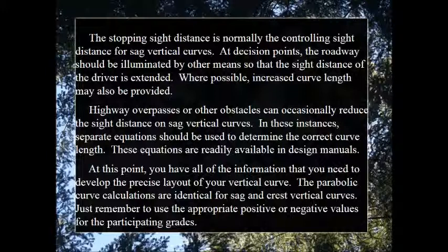At this point, you have all of the information that you need to develop the precise layout of your vertical curve. The parabolic curve calculations are identical for sag and crest vertical curves. Just remember to use the appropriate positive or negative values for the participating grades.